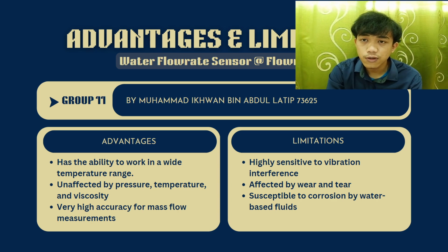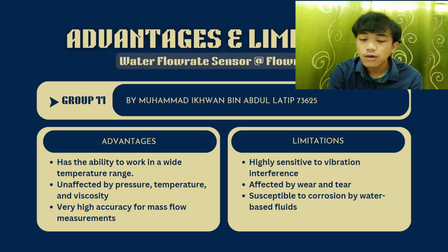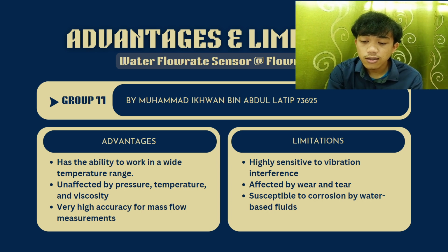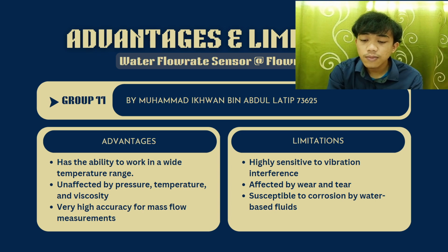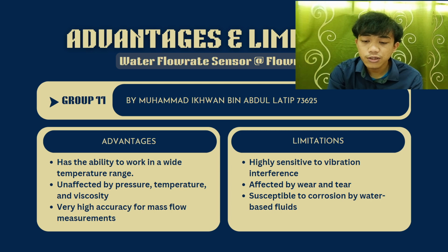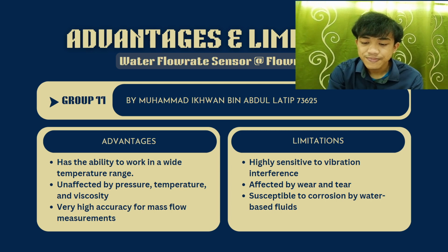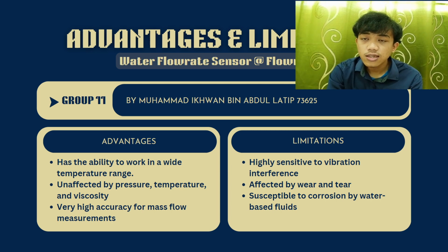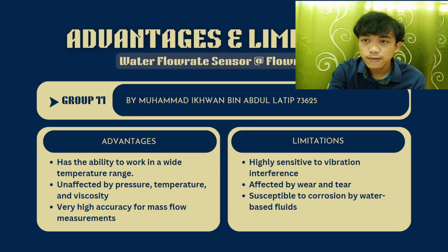The limitations for this sensor are that it is highly sensitive to vibration interference because it requires water to flow through it. It is also affected by wear and tear because in long-term use, the movement of water will give a lot of friction to the sensor. It is also susceptible to corrosion by water-based fluids.